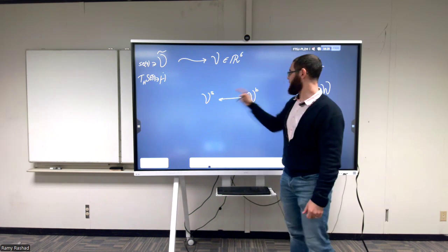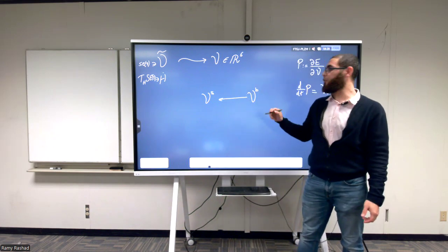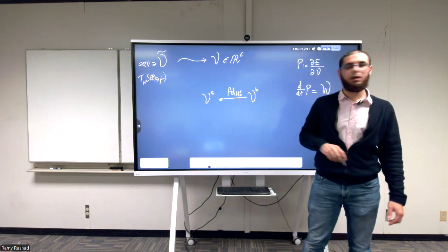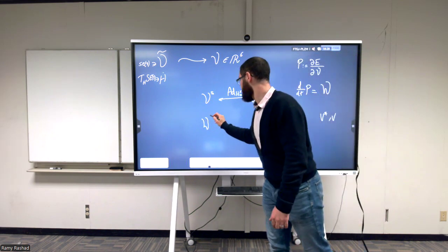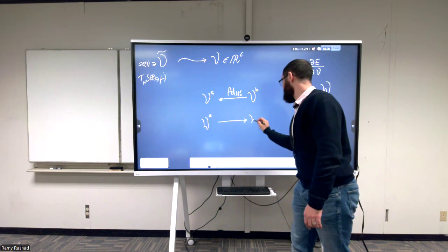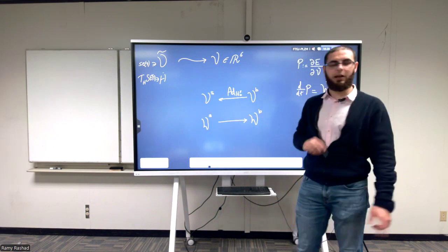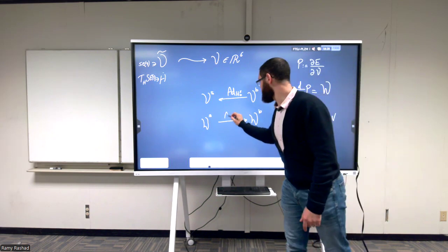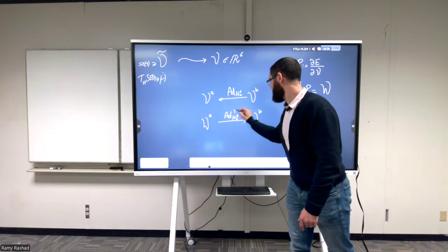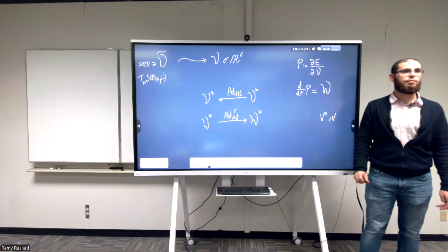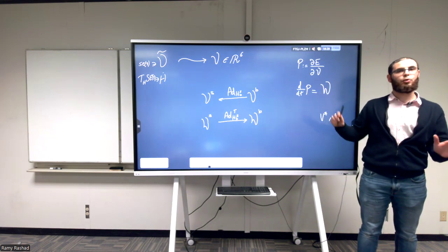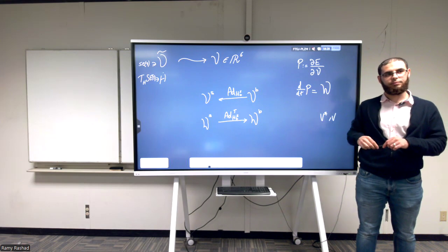transform it into the twist in the B frame, we use the adjoint from B with respect to S. If I have some wrench in the S frame, and I want to represent it as the wrench in the B frame, I need to use H B S transpose. For now, take it as a law. Next time, we're going to be proving it, starting from here, inshallah. Okay. So thank you very much.